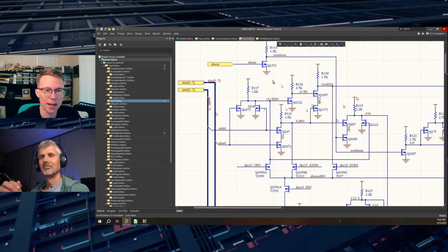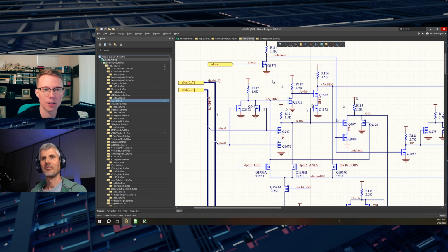And the problem is that, number one, you need enough parasitic capacitance on the bus so that pre-charge will last from one cycle to the next. The one-stay ones, yeah. And at the same time, you need to be able to pull them down quickly enough that they can get latched properly into the inputs of those other registers. And that's limited by the characteristics of the transmission gates that are used to gate those onto the bus. And I didn't have any choice there because there are very, very few 4-terminal MOSFETs that you can buy now.